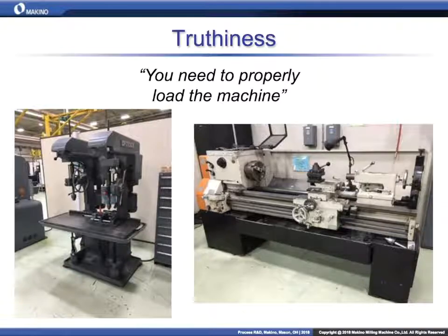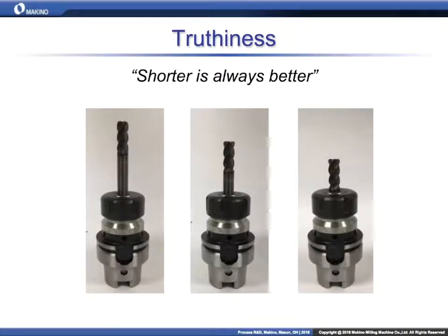So, moving on to the next one, truthiness. People say when you're having chatter, shorten your tool. Shorter is always better. 99% of the time, that is absolutely true. Okay, that's a good one we can hold on to. Yes. Now, whatever feature you make, your tool needs to be long enough to create whatever feature you're trying to create. But your tool shouldn't stick out much longer than what we've shown here in the picture.